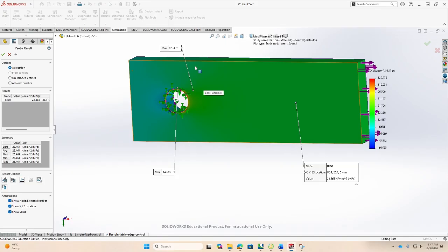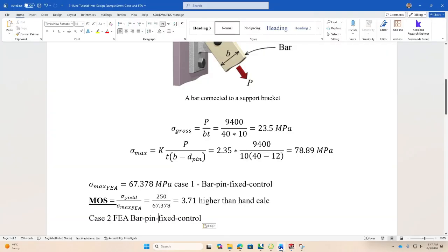But what I'm trying to demonstrate here is you can't just go blindly looking at some colors in the FEA software and think that you've got the correct results. You have to go through the process to convince yourself of the authenticity of the results, and then pick the ones which make more sense. So in this case, the margin of safety should be calculated based on this 129. So I will now use this name over here.